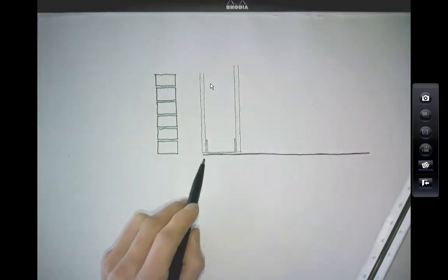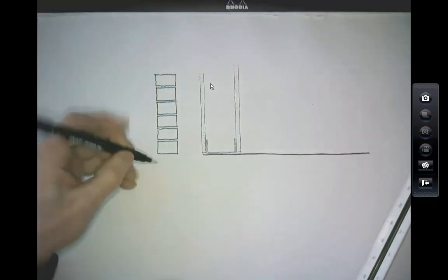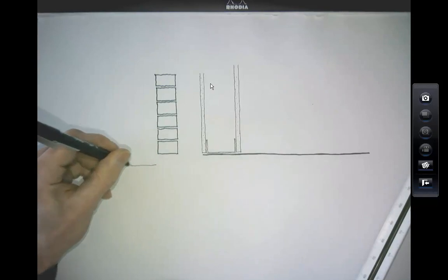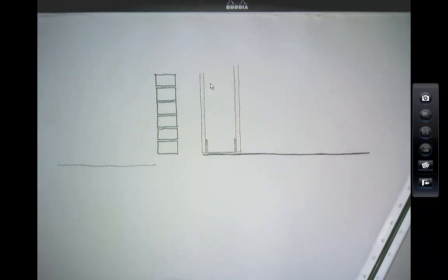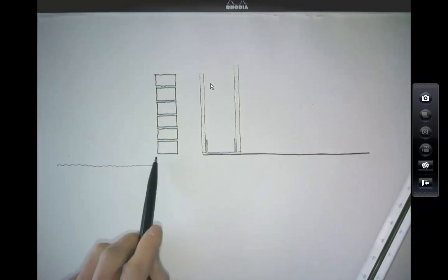But if I draw our outside ground level as here, and we just continued that concrete slab across, it's going to be sticking up out of the ground, which is not, you do see that sometimes, but it's not really a very good detail.